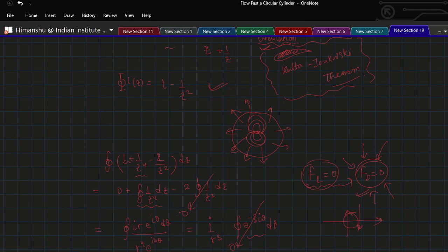But if you observe, the drag force is not 0 always. This is known as D'Alembert's paradox, and that we can't ignore viscous effect to its full extent as 0. There is a boundary layer separation after which we could ignore that, but before that, just along the contours of the cylinder, we can't ignore that. This was all that we are dealing with.